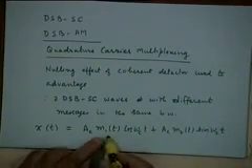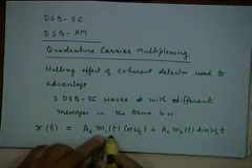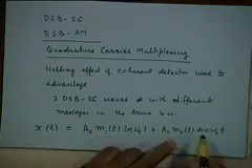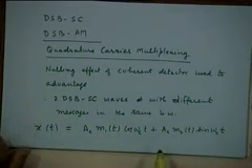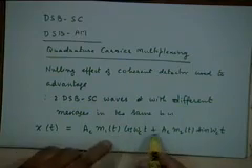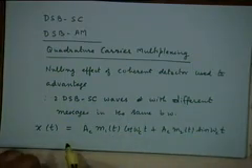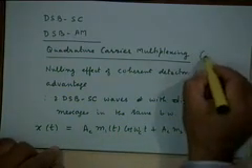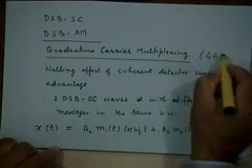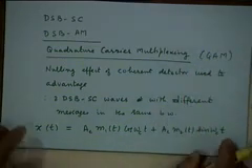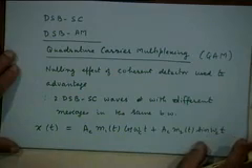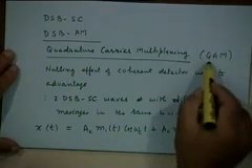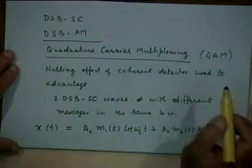Then I can reconstruct m1(t) independent of m2(t) and vice versa. So basically I have multiplexed two message waveforms onto the same carrier. This we call quadrature carrier multiplexing, also called quadrature amplitude modulation, QAM.